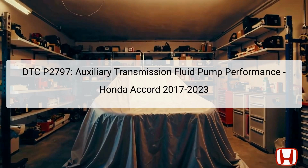The DTC Diagnostic Trouble Code P2797 pertains specifically to the performance of the auxiliary transmission fluid pump in Honda Accord models from 2017 through 2023. This code is indicative of an electrical circuit issue related to the auxiliary transmission fluid pump, which cannot stem from any mechanical failures within the transmission itself.